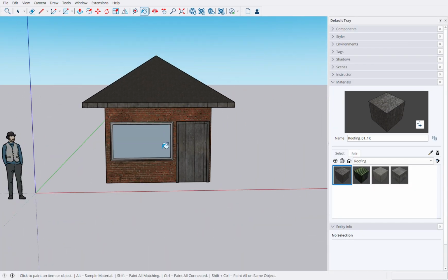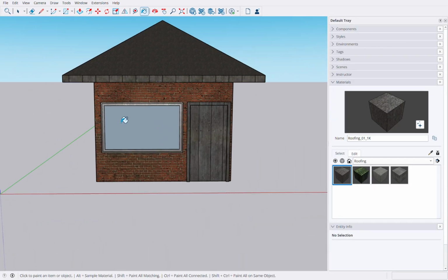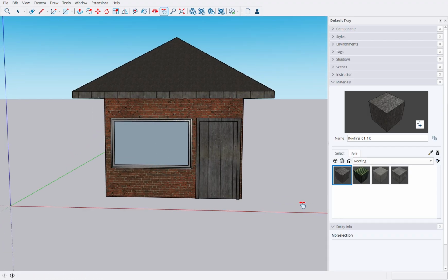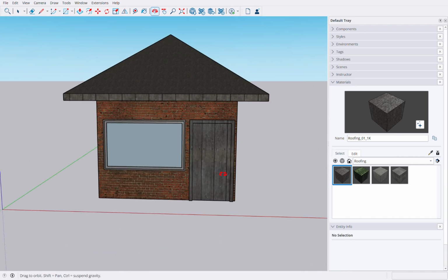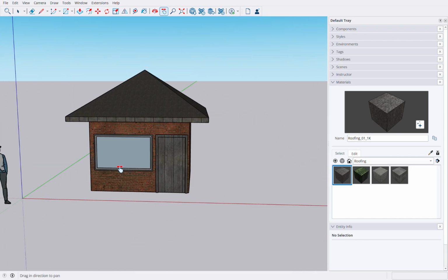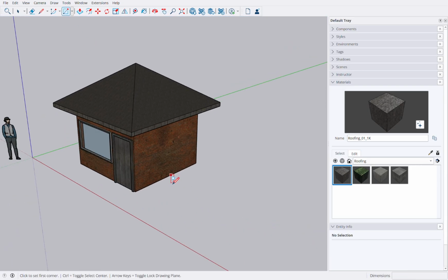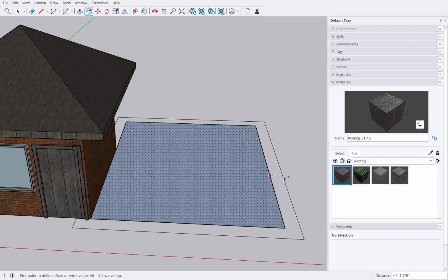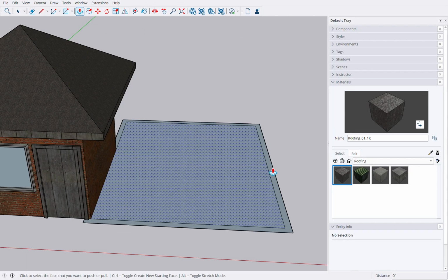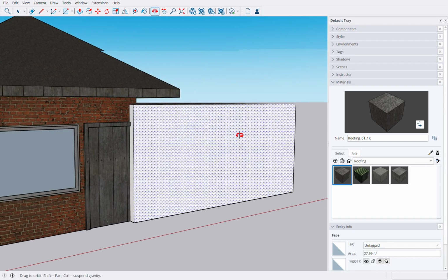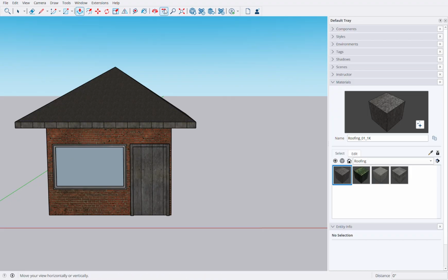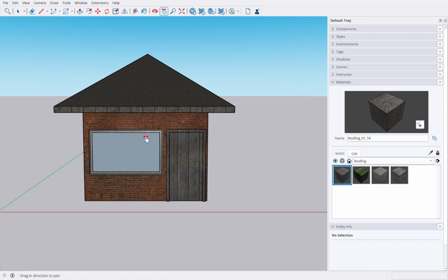Now, this is a very basic exterior, very basic structure, but it doesn't really change no matter the scale. So from here, we have this house, and we could add on to it if we wanted to, and that's totally up to you. So what we could do is we could add another square. So we want that, and just basically repeat the process. So what we did was we offset 6, and then you can pull it up and you can create another structure to it. So it's all the same, no matter how you want to do it. That's just a very basic way to build your first structure in SketchUp.